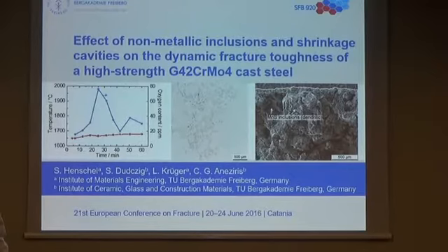and we can see also some certain nonlinear behavior prior to the instability point. The instability point is here, and it could not be seen very well here, but this point of instability is detected by the strain gauge near the crack tip. Prior to this instability there is some stable crack growth, and afterwards there is the unstable crack growth.